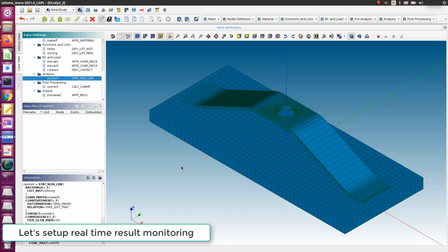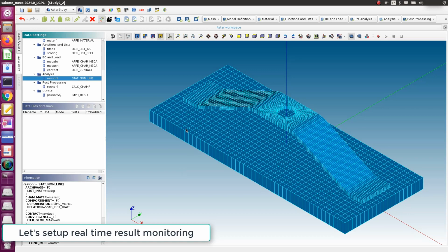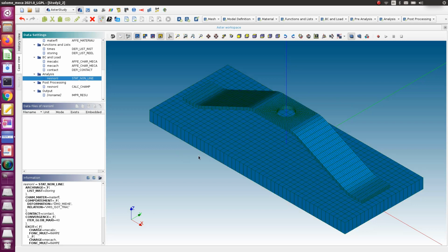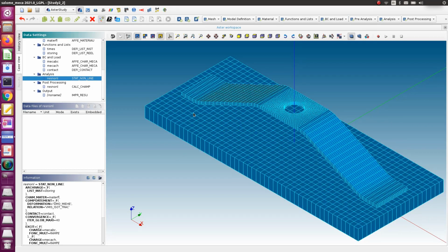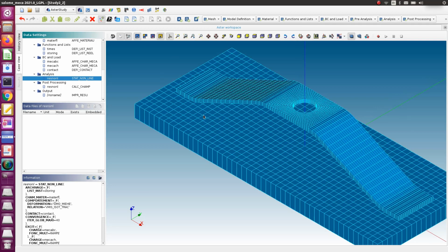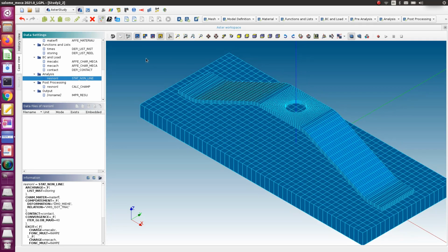And I still had one thing I really wanted to show you. Let me think quickly. Yes. When you do nonlinear analysis like that, one thing which is very difficult is you don't know what the value of displacement in the contact area is when you solve. Well, there is good news about it. There is an easy way to get the value of contact at a specific node during simulation, without going through ParaViS or anything like that. So it's really useful. Let me show you how to do this.